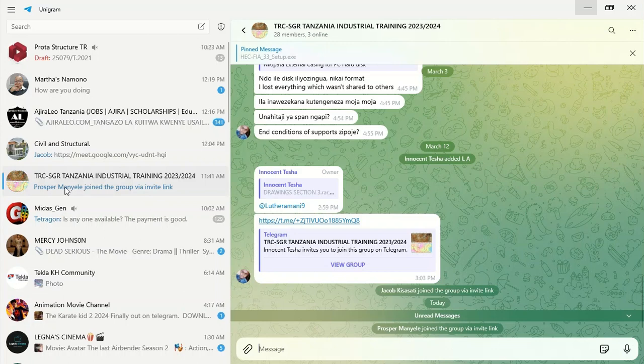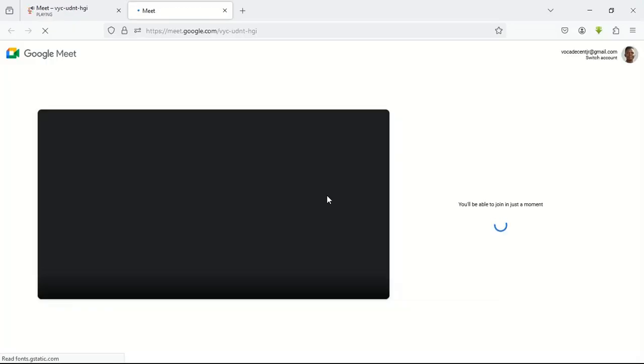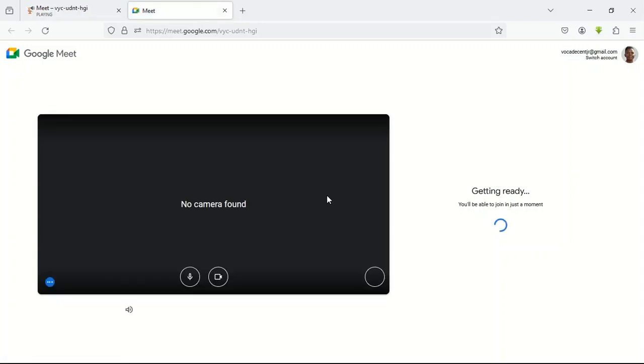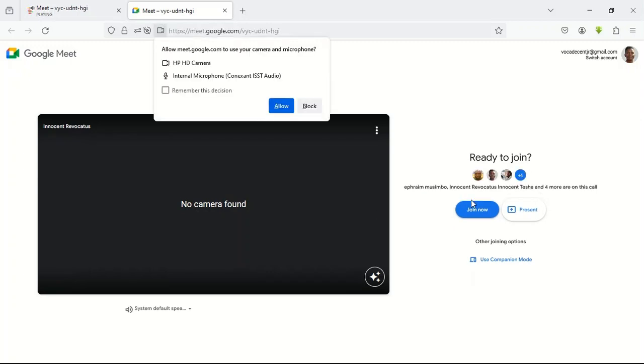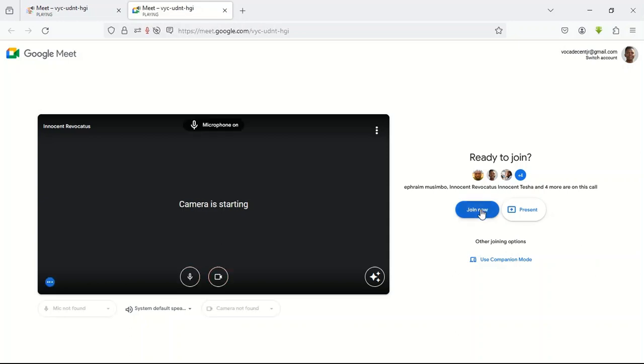If you can remember, we don't have this beam. So this one is perfect. I think this model is good up to that point. What we are going to do now is push these columns to come in. In ETABS, columns will just go to their respective spaces, but it is difficult to create the grid systems. In ETABS we had to select the nodes, then use the nodes to create the grid lines. But for this one, columns and grid lines will just be okay, but now we have to push these columns.